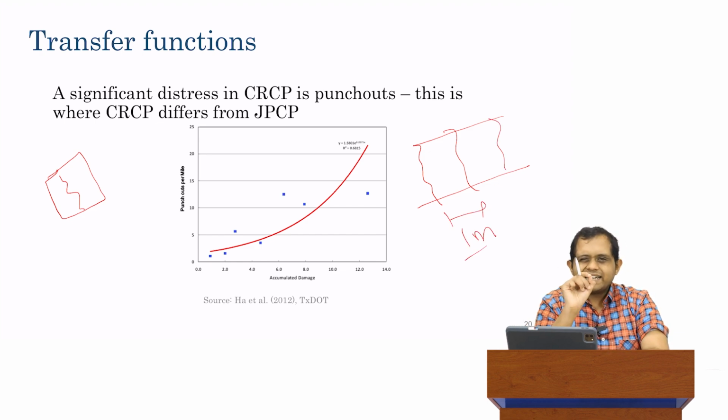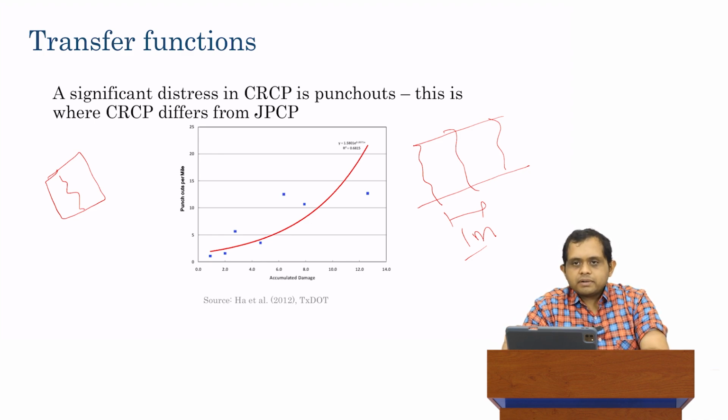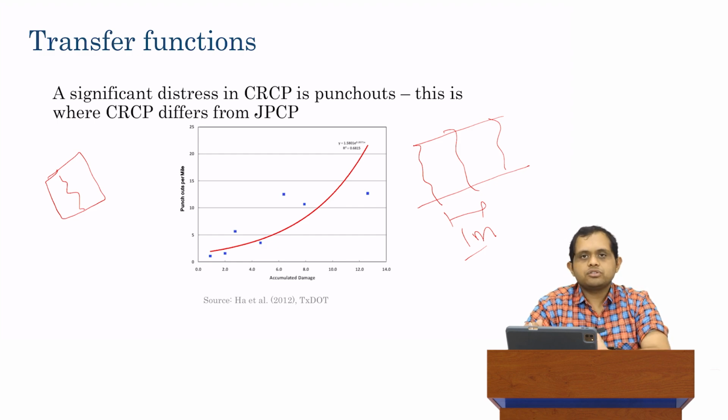So we have these very tight cracks with very, very small widths, these hairline width cracks. Ideally, the cracks should be parallel to each other in the transverse direction. That's not a distress, that's exactly how it's supposed to behave. Because these cracks are so small, the width is so small, it's very smooth for drivers to drive on them, so we don't call them a distress.